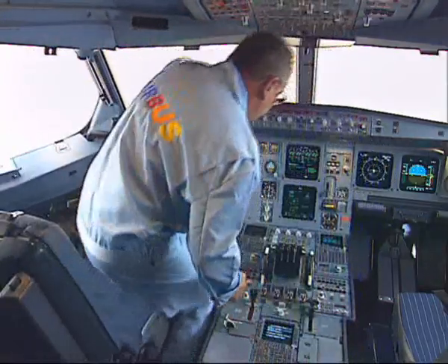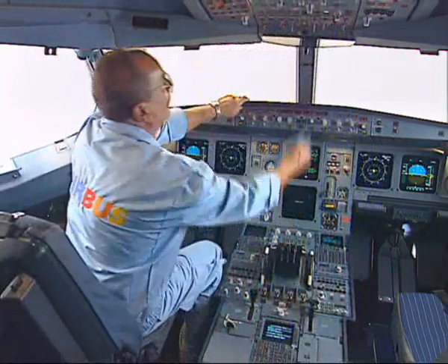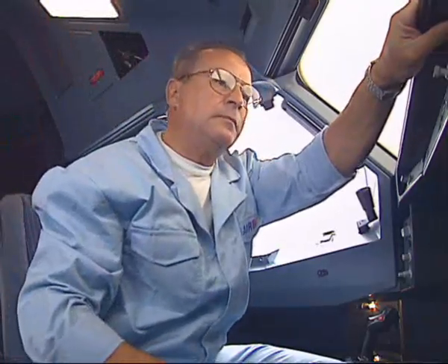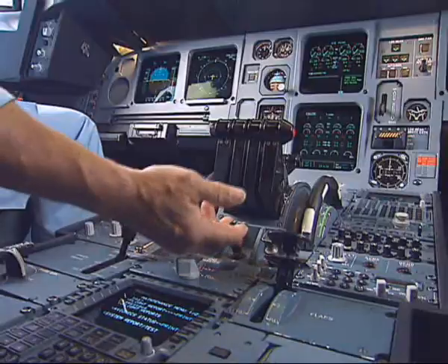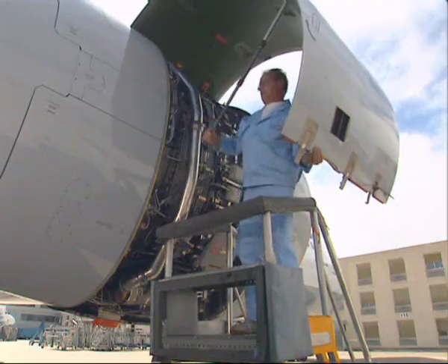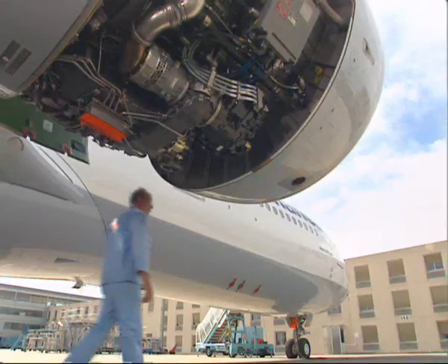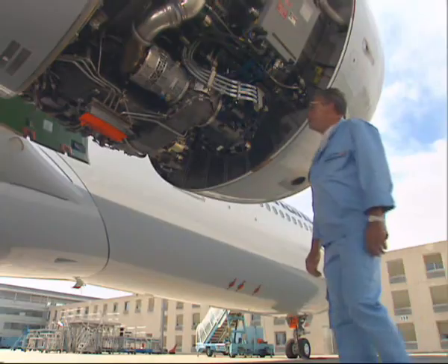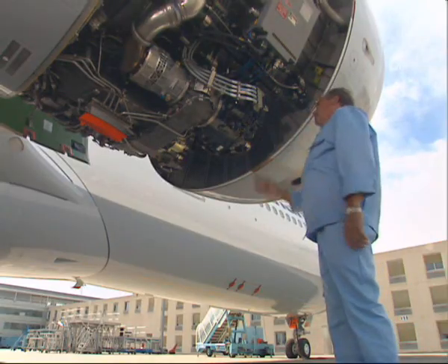Do an engine dry motoring or start the engine at idle for at least 2 minutes to allow the oil to circulate through the system and ensure that every cavity of the oil system is properly filled with oil. Let the oil level settle down for 5 minutes.